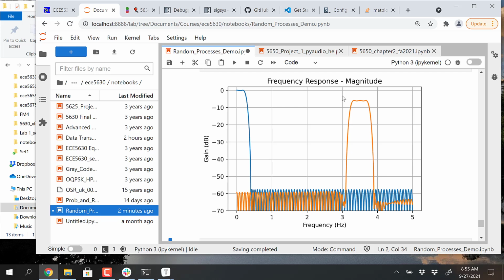But now what I can do is, I've got a bandpass filter designed, and I can go ahead and pass some white Gaussian noise through it, and then just play around with calculating the power at the outputs of the filters. And then I can do the in-phase and quadrature parts and so on to synthesize it back down to complex baseband. Complex baseband means this filter will be used to obtain in-phase and quadrature noise, not just the real part. I just synthesize the filter using the real part, but I actually have to have the two components.